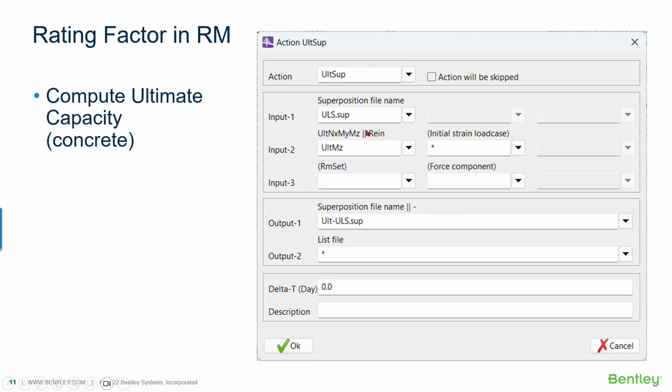So from this envelope, you understand that we have an envelope that is directed by different values. So we will take only the page where the ultimate MZ is given, both in maximum and minimum. And in that case, keeping all the other values, the same N, the same shear, the same cross moment, and so on, we increase the ultimate MZ to a value corresponding to the maximum strain admitted.